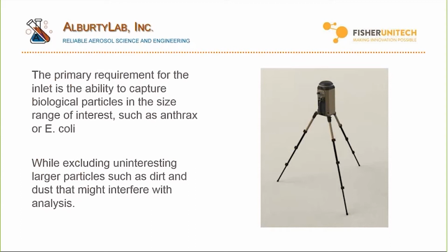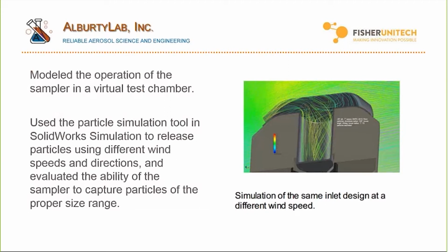So what they want to be able to do is actually concentrate particles so that they can detect them sooner. And so they are using SolidWorks Flow Simulation to track particle studies, particles of different sizes, and where are they ending up, and can we concentrate them in this detector to detect them sooner. So they use SolidWorks Flow Simulation to model their chamber, and there is a capability in Flow called particle studies. So you run a flow simulation, develop your external flow fields, and then we can start putting in different particles of different sizes and different initial velocities and track where those end up. And since our goal is concentration and detection, whereas oftentimes people are looking to get rid of particles for things such as air quality indices and HVAC types of simulation.